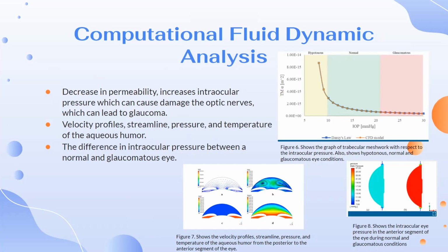Computational fluid dynamics helps visualize stress, strain, and deformation of the iris and cornea. It is also important to understand that the shear stress and shear strain of aqueous humor can cause deformation on parts such as the iris and cornea. The highest area of deformation is near the center of the iris. This is believed to have happened because the aqueous humor travels in between the iris and the lens, which has a narrow cross-sectional area, which increases the velocity of the aqueous humor.